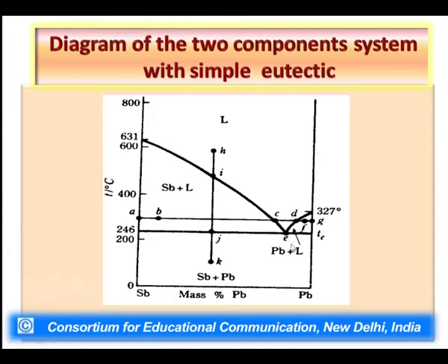So, what they used to do is have lead and antimony fused and mixed together, and then heated with the iron rod, and that wire used to contain these two metals. When the rod heats it, it leads to melting of that alloy, which is made at eutectic composition, at a much lesser temperature compared to antimony or compared to lead.